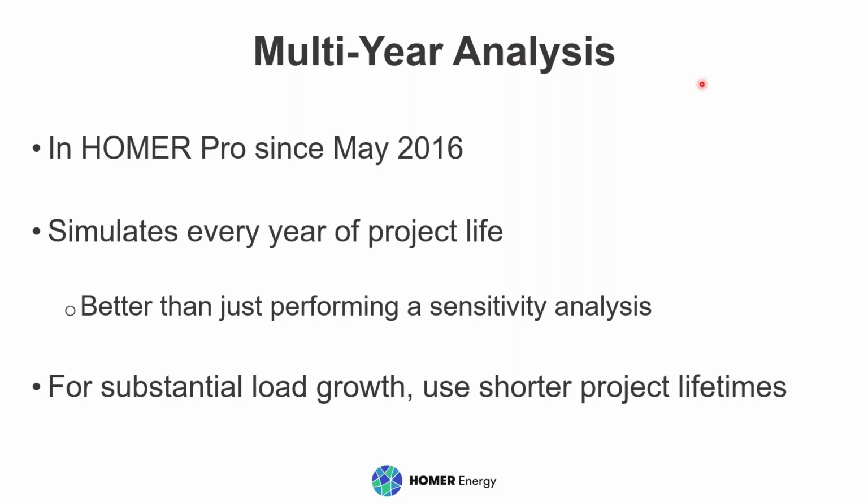Now that the microgrid industry is becoming more of a commercial industry, you don't want to overbuild initially. And if you're treating these microgrids as a commercial venture, you're going to be in close contact with that community, or the facility anyway. It's much more cost-effective to break it up into periods, and if you're expecting significant load growth, go and enhance the system later. So instead of doing a 25-year project, you might want to break it into smaller projects and evaluate when it would make sense to enhance it. I just wanted to point that out.